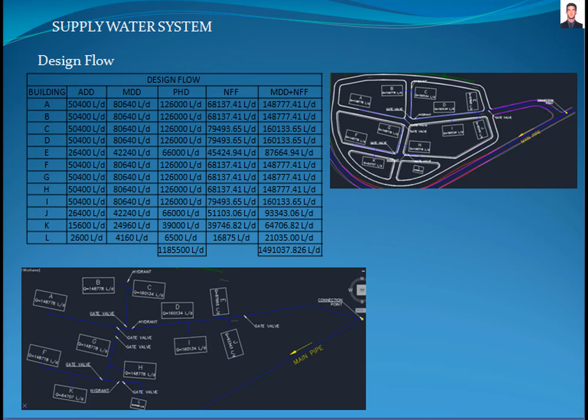The valves shall be placed so that a pipe break will affect water service only in the immediate area of the break. A hydrant shall be placed at the dead end of the line, at the highest point of the system, and at an intersection.